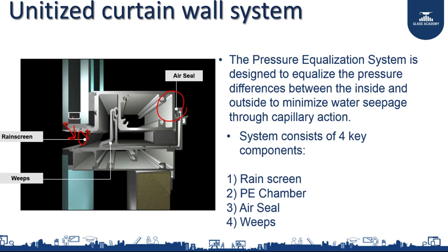If your air seal breaks, even if you put a pinhole here, a small hole, they will suck inside. So, be careful when you are attending to a design, whatever form, you must ensure your air seal is in order. So, this stack joint, as I explained, is designed for movement.